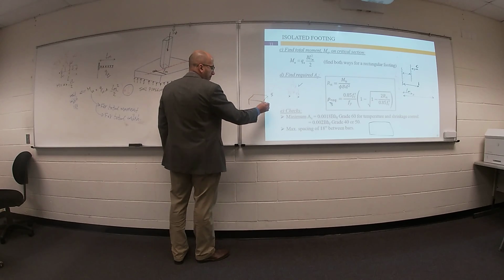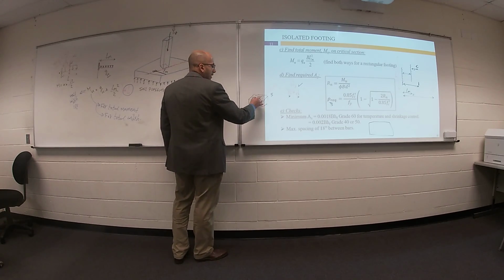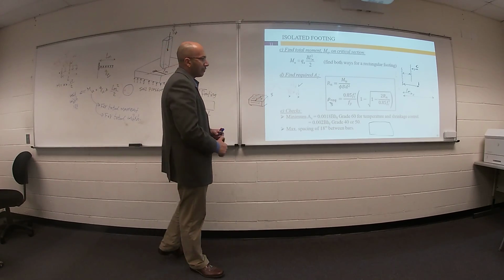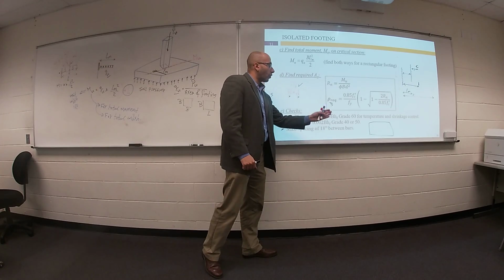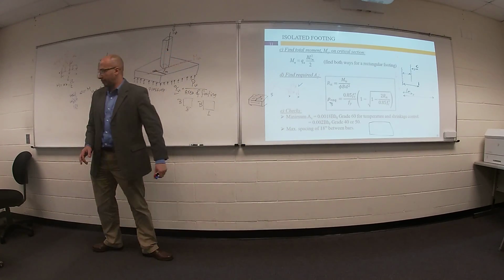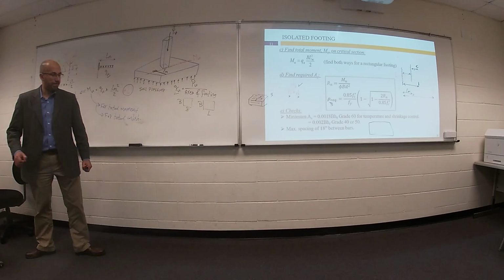For your footing, once you determine how many bars, please go ahead and determine the spacing between two bars. This spacing must be 18 inch or less. We will see all of these steps during our exam.